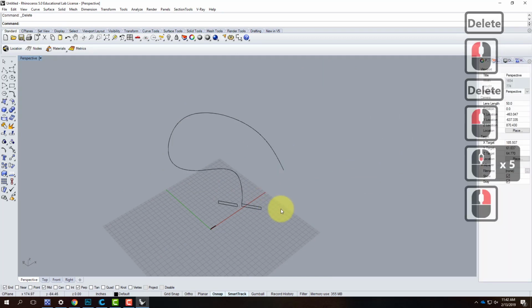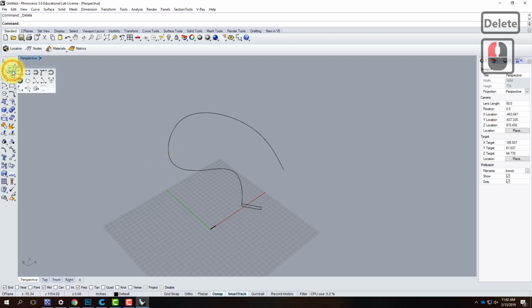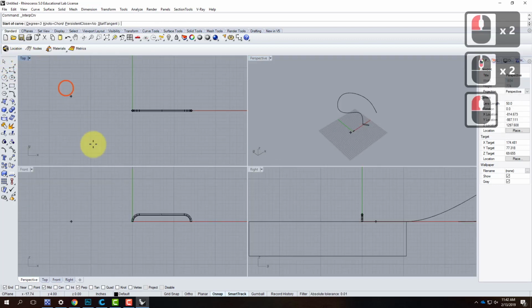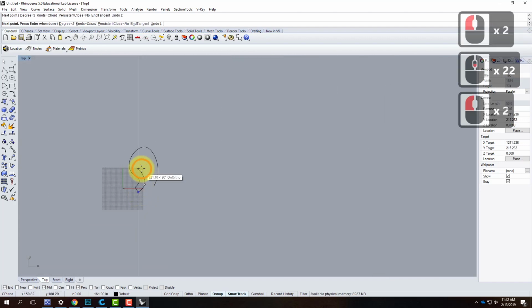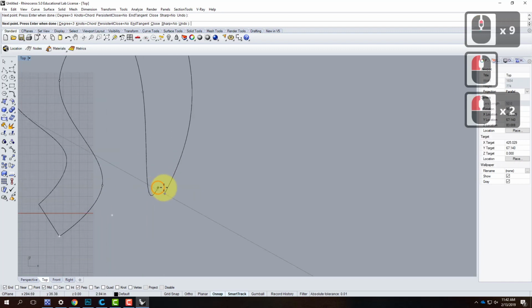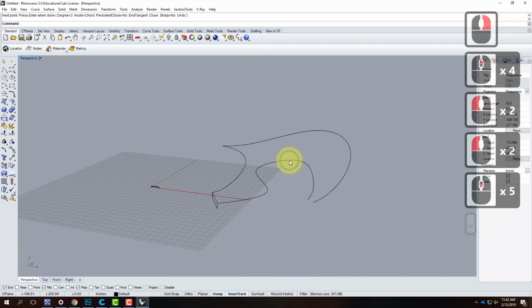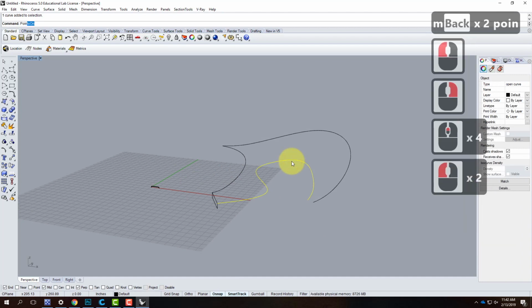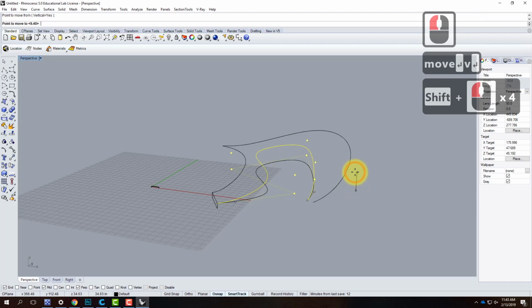We also have the ability to do what's called a sweep 2, where we have 2 rails. So let me add real quick another curve that is inside of the first curve. Oh, let's go outside of the first curve because, well, yeah. So I just gave myself another curve here. Let me turn the points on so I can make a few adjustments. Just move those up a little bit, like that.